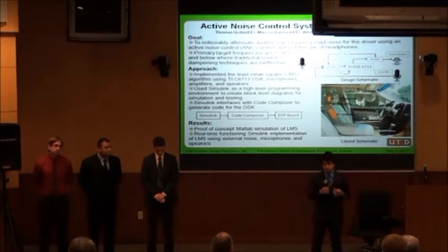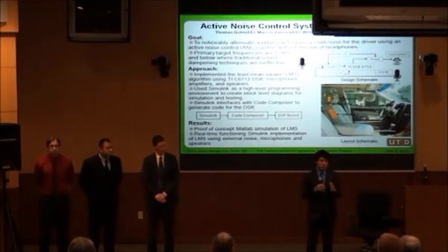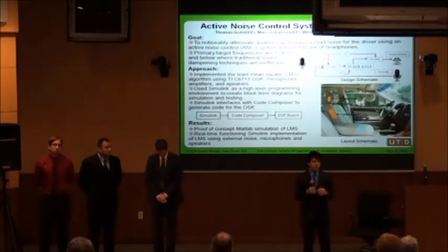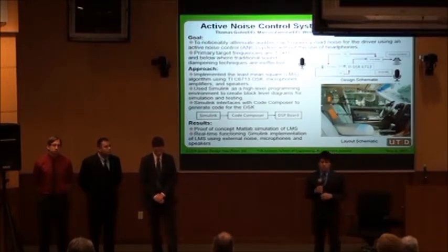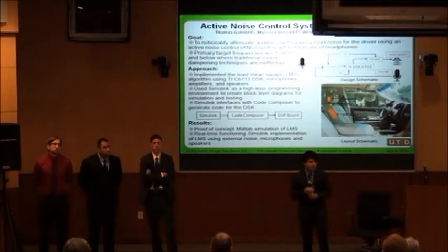What we wish to improve is making the LMS algorithm more stable, because at the moment, it likes to blow up. You can tell in our simulations and our testing that it's trying to adapt, but it just doesn't adapt as well as we wish it did. We also have to make it more compact. Since this is a system that we have to implement into cars, we wish it would be smaller so we can actually implement it, but at the moment, due to the amplifiers that we have and other equipment, it's much larger than we initially expected.